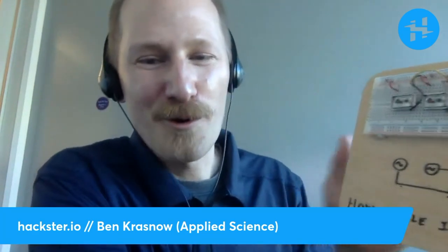And I'm running both oscillators. They're both the same frequency, or they're spec'd to be the same frequency, but they're beat together and then amplified. And so I brought a little audio amplifier. So the trick is that quartz is actually very temperature sensitive. And so if you just put your hand near one, you hear the frequency change, or if you blow on it.